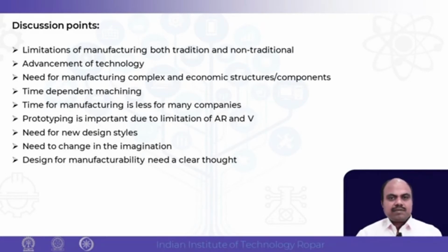The traditional machining process includes CNC machining. CNC machining is much more accurate, but it takes a lot of time. It takes a lot more time to make the product, because we need to understand the product, make the CNC code and put it in the CNC machine, and even then, depending upon the complexity of the product, we need 5-axis, 7-axis CNC machines.